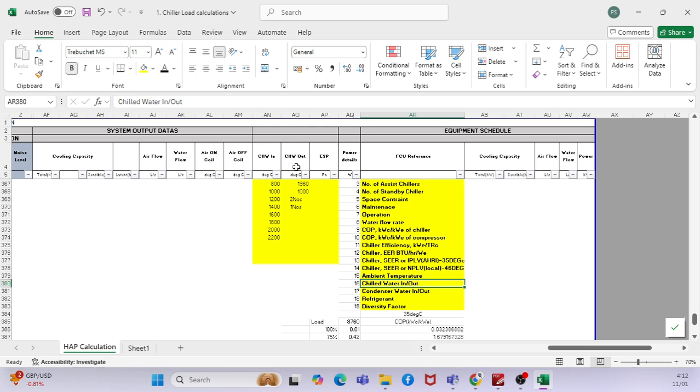One thing I wanted to understand as well: from my experience where I've done fit outs, you already know the chilled water temperatures in and out, because the chiller is designed for that. Exactly, so based on that you select your indoor unit for the fit out. You can change the temperature for the fit out when you do the selection of the FCU.